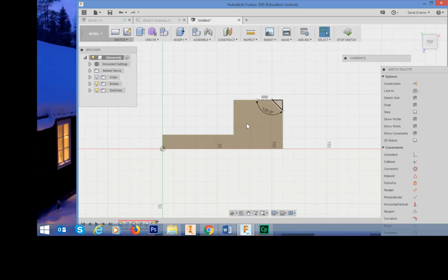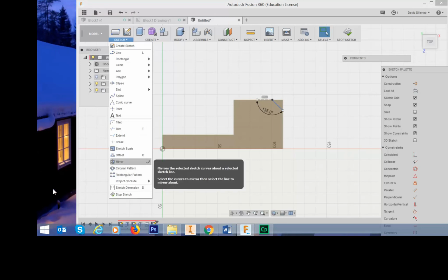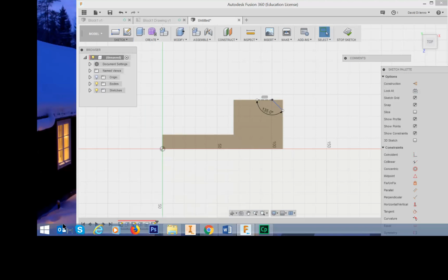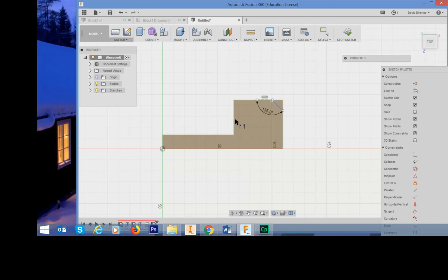Now, if for some reason that doesn't suit me, I wanted to have a smaller chamfer, I can go to my favorite little dimension thing here, click on dimension, which escapes me at this point in time. There it is, dimension. And I can say, all right, well, I want that distance to be from here to there. Come on, you can do it. There to there. Drag up. Nope. Yeah, we should be able to get myself a dimension from here to there. That's 45. I don't quite want that, so I'm hitting the escape button. I want the dimension to be from this point to that point.